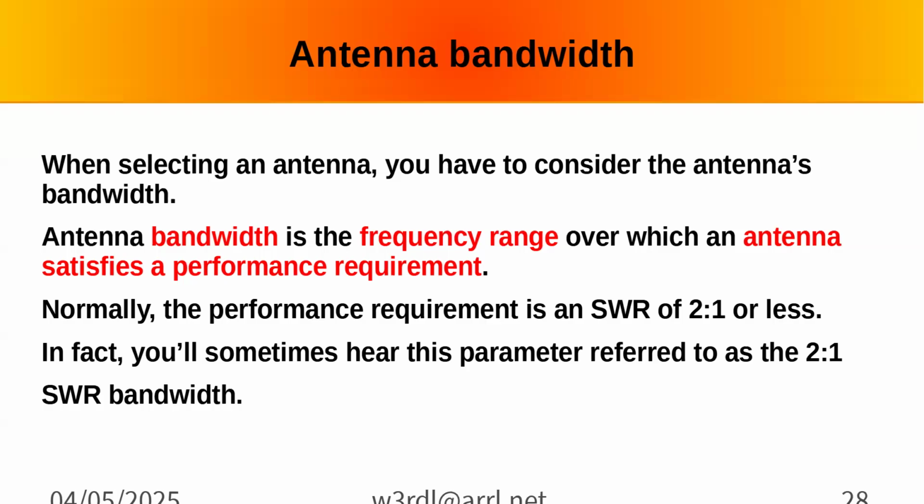And you can definitely match it, since most transceivers have a built-in tuner, and they'll usually go 3 to 1 unless they're in emergency mode, and then they can go 10 to 1. The 7300 will do 10 to 1 in emergency mode. Half power or less. No, it starts cutting back at 3 to 1. Yeah, I think so. It'll do 3 to 1.